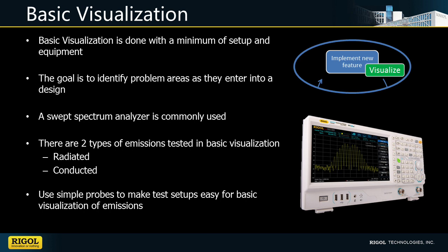Typically, we'd use a swept spectrum analyzer in this kind of mode, and the goal from an EMI pre-compliance standpoint is a simplified setup. This is on your bench as you're trying to implement new features. You don't want a complicated setup room you have to go into. So we're going to talk about different setups that are very easy to use and made for your benchtop, for your desk.